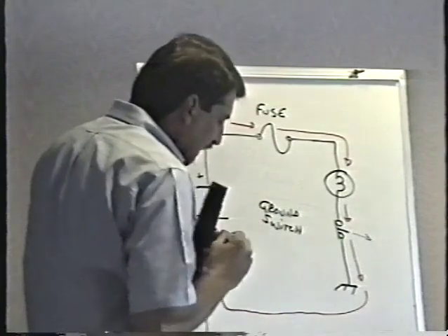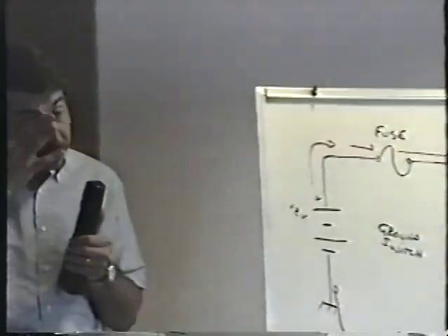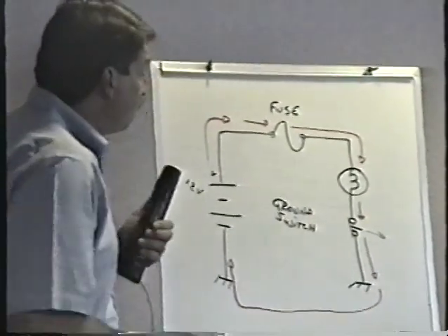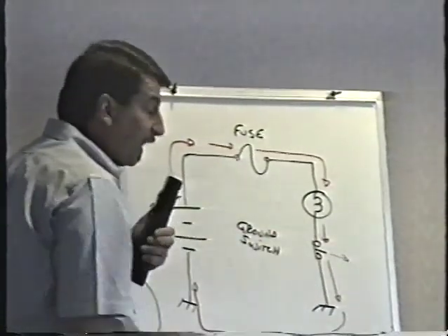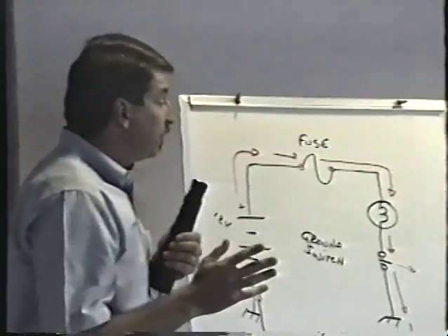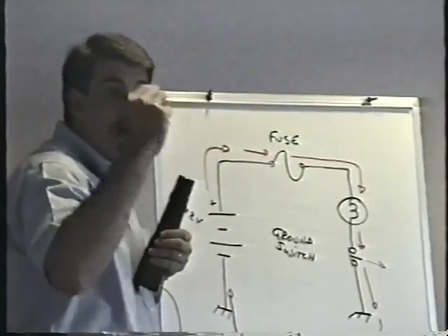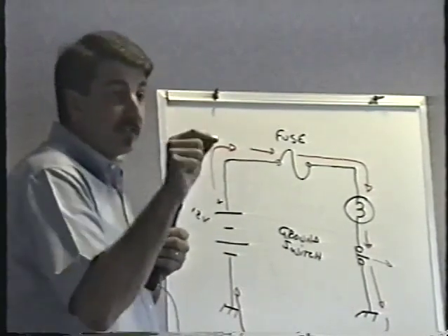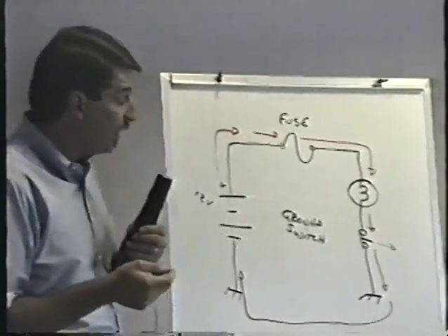And this is actually the most common way to control things in electronics. When we're dealing with electronic controls, like turning light bulbs on and off, we very often use a ground switch. Instead of switching the source in and out, we simply switch the ground in and out. Pinball machines are the same way. We'll see this on Saturday. In a pinball machine, there's always power going to the coils, continuously, the whole time the game is plugged in and turned on. To energize the coil, they ground one side of it. The ground is switched in and out. You'll see what I'm talking about later on.